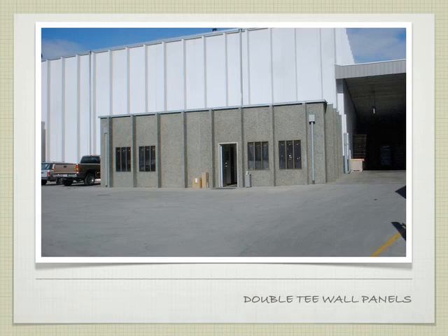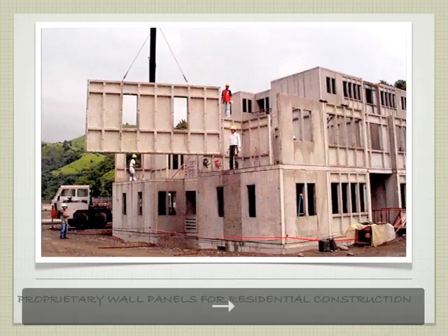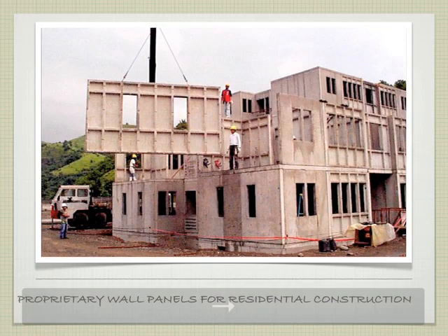Another example here. If you look very carefully, you can tell this is a double T. There's a line there and a line there for where they seam together. In this particular example, we have some windows cut in the front building, not in the back building. Notice that the windows fall very symmetrically, exactly in the center of one of these panels, and so it makes it a little bit easier. Could we have a window that spans one of these T's? That would defeat the purpose. So you're very limited in what kind of apertures can go through that particular wall.